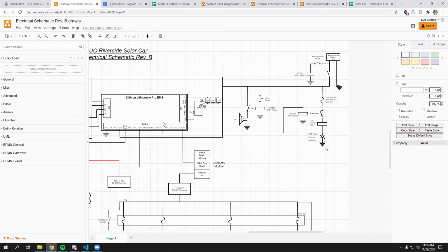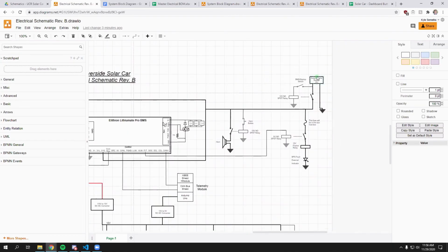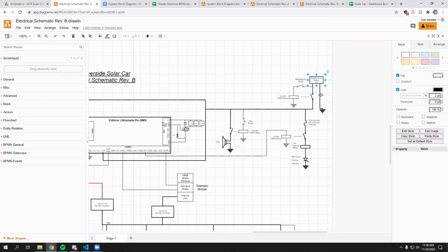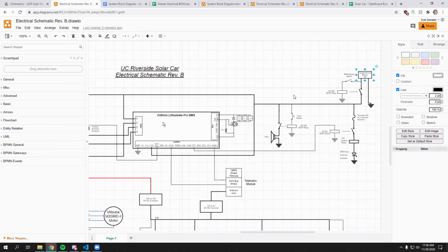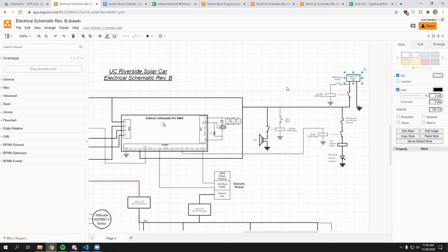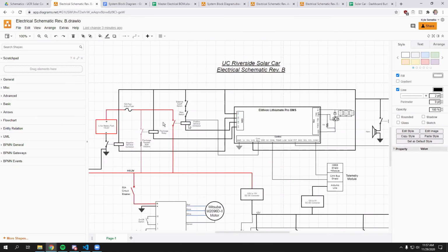Yeah, those are the big things. This one we call the supplemental battery. It's just going to power the BMS basically. Yeah, I think I've seen the BMS already. I remember it having fans and stuff like that. Is it mainly to power the fans, or is it to power something else? It's to power the BMS because these coils control these contactors, which isolate the battery pack.